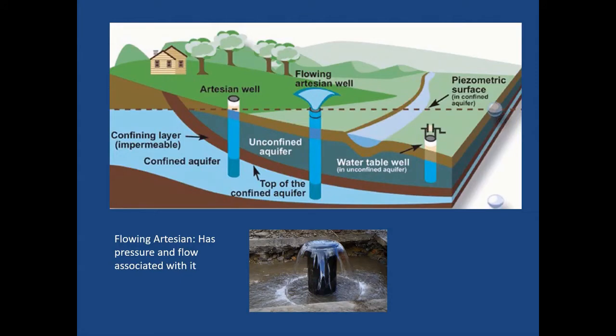Basically 4 different types of water availability from a surface standpoint. Don Leisky will talk about the collection of rainwater, but we can use the river or streams, ponds, lakes for fresh water. The most common type of well is the water table well that you see on the right. That would go into an unconfined water aquifer, and that water would be accessed and seep in to the level